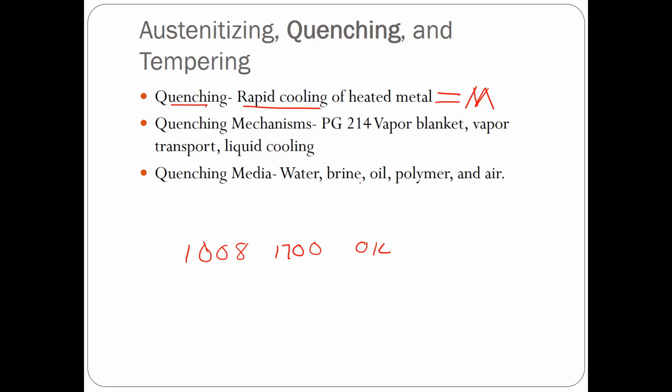did I quench that material? No, because my product is going to be perlitic. It's going to be perlite and ferrite. It's going to be perlitic. So I did not quench it. Even though I dipped it in cold oil, that's not going to get it.